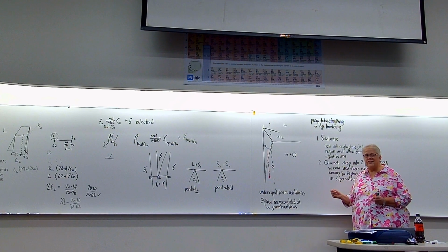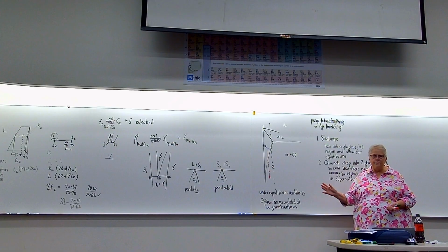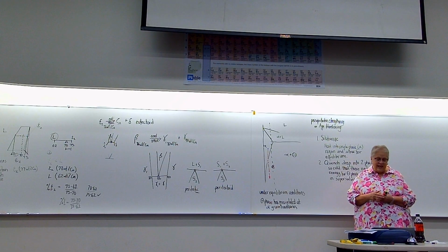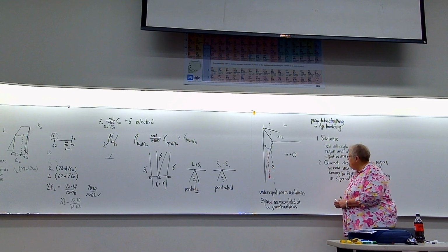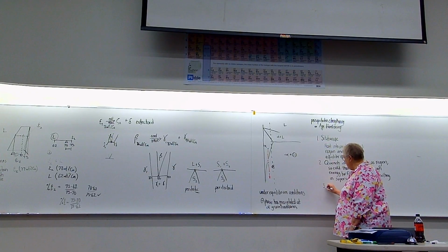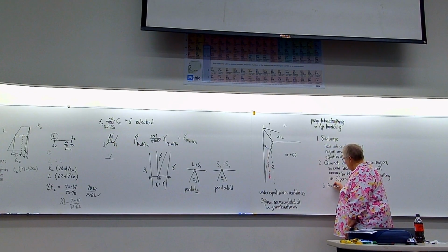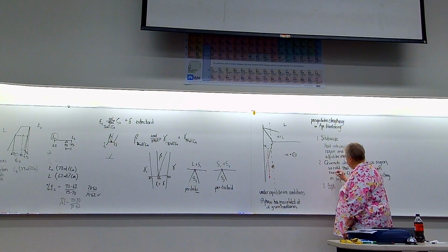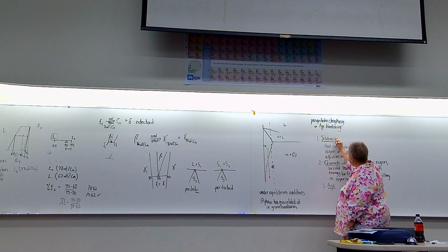Okay, third step, and this is the step where everything happens, this is why it's called age hardening. The third step is called aging. Solutionize, quench, age.